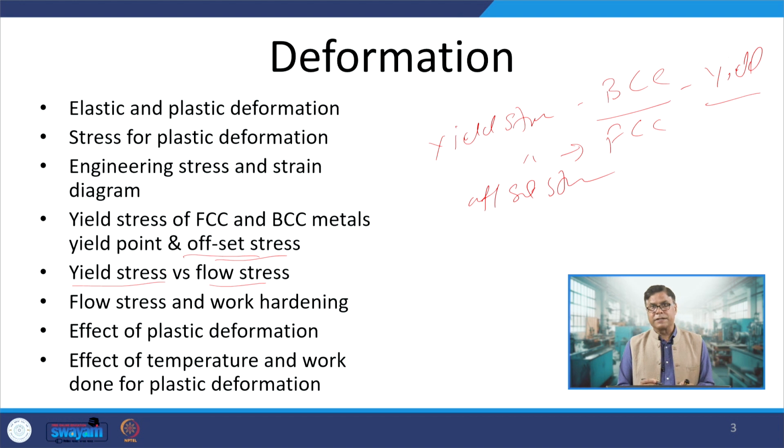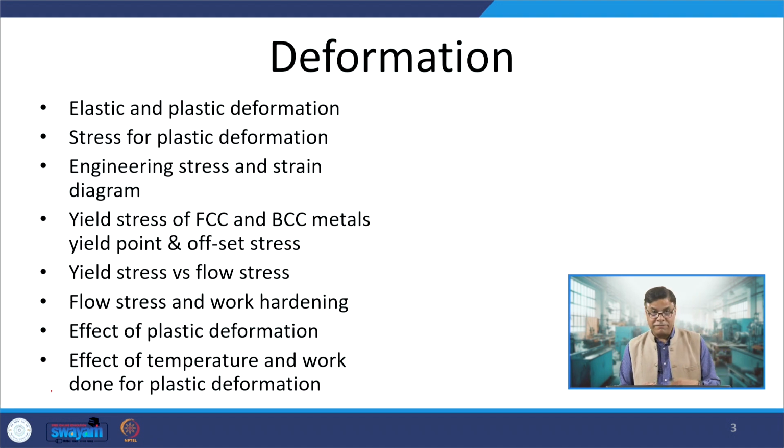Yield stress corresponds to the stress required to cause the plastic flow of the material in annealed condition, and the flow stress is the stress required to cause the plastic flow of any metal, including the metal in annealed condition. So, flow stress can be the yield stress or any other value. If the material is in any other condition, like work hardened condition or metallurgically transformed condition, that leads to a different stress required to cause the plastic deformation than the yield stress, then to have a clear value of the stress at which the plastic deformation will take place, we use the flow stress.